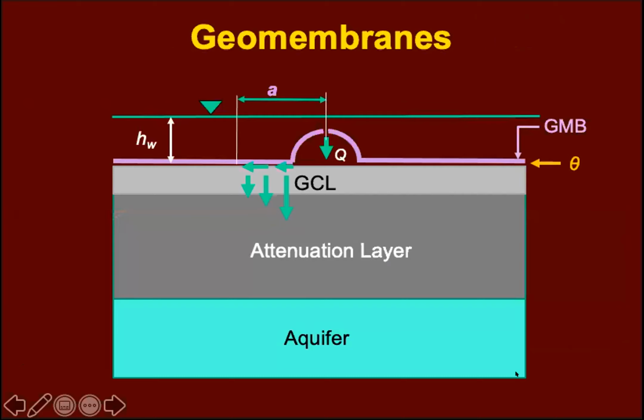So if a hole is present in a wrinkle, the wrinkle will act as a conduit for storing fluids. And due to the lack of perfect direct contact discussed earlier, leakage and flow will not only develop beneath the wrinkle itself, but it will develop along a certain wetted distance beyond the edge of the wrinkle due to the lateral flow between the geomembrane and GCL layers.